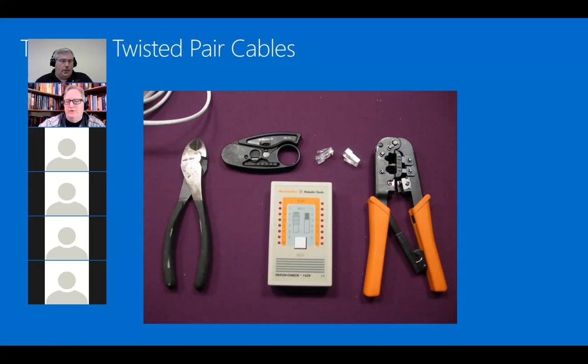On the other part where you showed the other modular connectors, where it's a little longer into the beds where those insulation cut blades are, you use a punch down tool, which some of the guys may have seen the phone man use, or even a network guy, where he's rapidly going across the connections and doing a double punch, which automatically pushes the wire through and then trims the edge off that wire. Then they'll inspect it to make sure that it's seated all the way to the bottom.